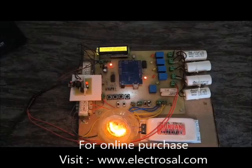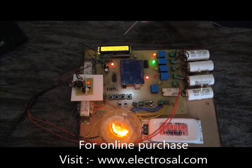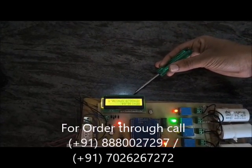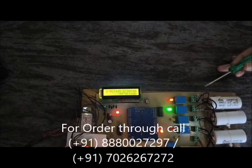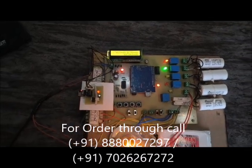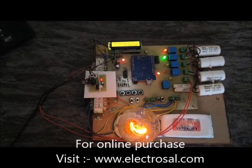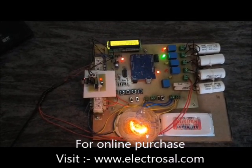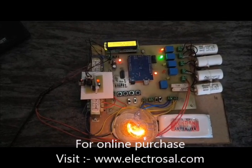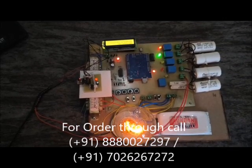In the next cycle, the system senses the change and we can clearly observe the current lag on the LCD screen like this. Due to this lag, the reactive power increases, the apparent power increases, and the real power decreases compared to the apparent power. This relationship can be clearly explained using the power triangle, where real power, reactive power and apparent power are related. The same effect can be observed here in our system.